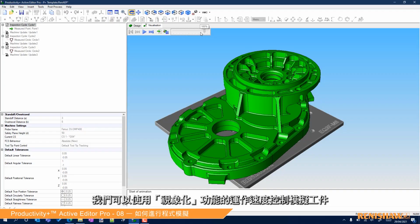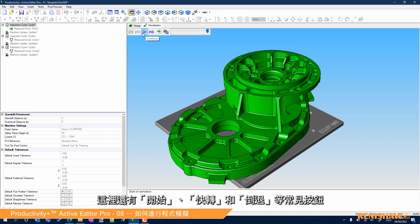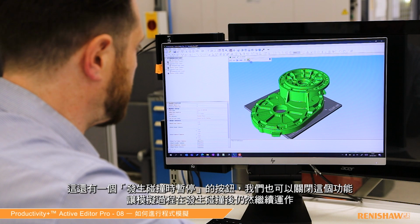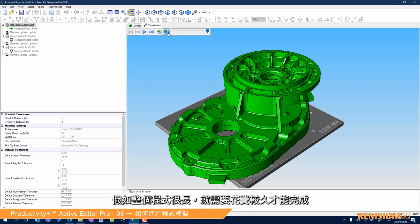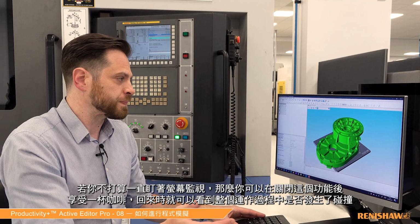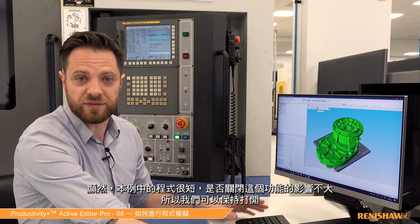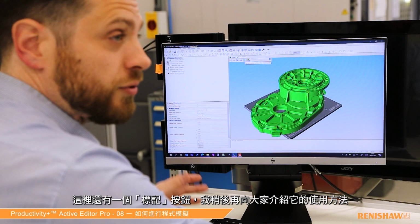So first off, we have the speed in which we're going to run the visualization. So I'm going to keep that at maximum. We have a play, we have fast forward, rewind, the kind of controls you'd expect to see. We have this button here, which is pause on collision. So you could switch that off and just let this run. If you've got a very long program, you might want to run it, go get a coffee, come back, and then see if you've had any collisions if you're not going to sit and watch the whole thing. This is obviously quite a short program that doesn't really matter too much, so that's where you can just have this pause on collision. There's also a marker which we'll come back to and I'll show you how that works.